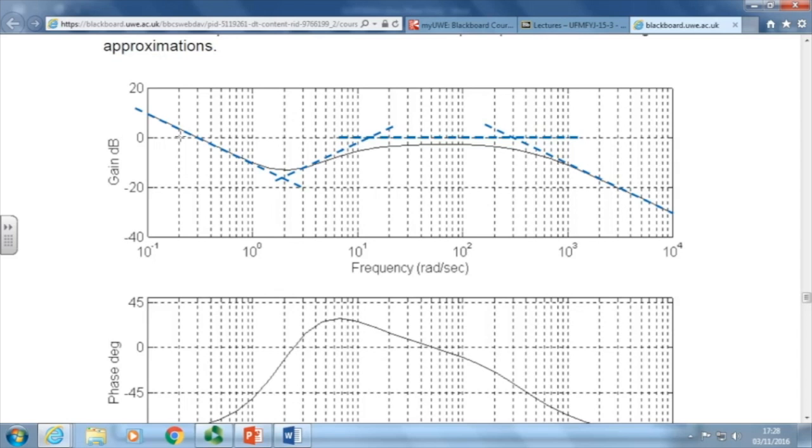Beware, these are logarithmic plots. The intercept on this axis is meaningless because that's not 0, is it? It's 10 to the minus 1. So with a logarithmic plot, don't get hooked into looking too much at where it intercepts the axis, because I could keep extending that axis leftwards as far as I like. So anyway, I've got minus 20 decibels per decade of slope.